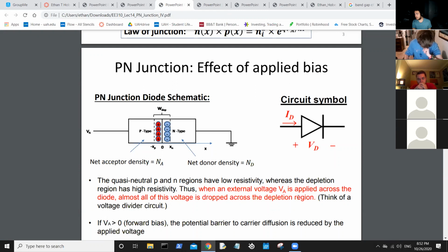So this is electrostatics. Obviously there's math that you can do to solve this, but if you illustrate it like this, it's the same effect, but a much simplified version. If you put a positive point charge next to a positive point charge, they repel. Same with negative point charges. So if you put negative, negative, positive, positive, it'll push the other ones together, decreasing the depletion region. You flip it like the question says, it pulls the depletion region apart, which means it's in reverse bias.